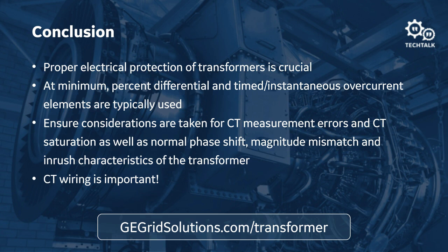All right, does the T60 with firmware 7.8 support full transformer differential protection using 61850-9-2LE process bus and MU320 merging unit? Yes, yes it does. I actually have a couple customers who have this installed on new projects or in the testing phase. So if you'd like more info on that, let me know.